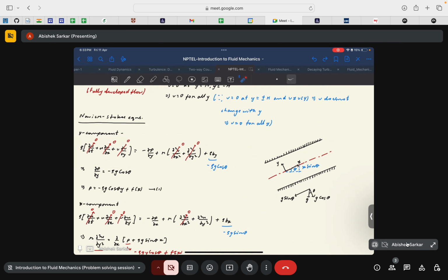Why I do not say momentum equation is because we have applied a lot of assumptions, the Stokes hypothesis, Newtonian fluid. Once you do that, it becomes the Navier-Stokes equation. It's not wrong to say momentum equation, basically again momentum conservation, but Navier-Stokes sounds more suitable.